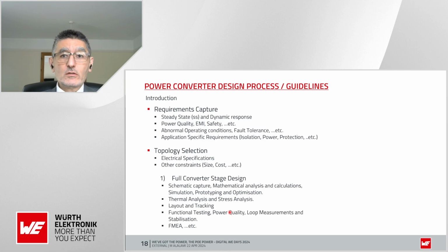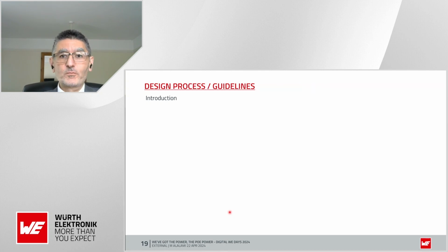From that point on, you're able to select the type of topology, the converter circuit that you need to realize these requirements. And from that point, you have one of three options. Once you've identified that topology, you can design from the ground up, from basically an empty sheet of paper, doing the full schematic capture, the full thermal analysis, the full design, functional testing, etc. On paper, which is an uphill struggle. It's a tough exercise, and you need to know your power supplies quite well.